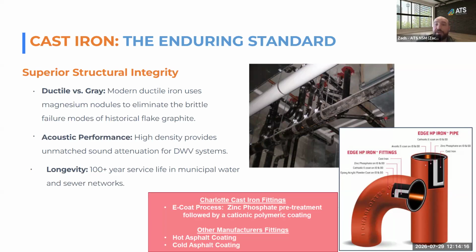But getting into unique applications like underground parking garages and commercial kitchens, where they have a high degree of FOGs, the fats, oils, and greases. That grease can off-gas and release highly corrosive gases into the piping. So even though the water with the fats is not necessarily highly acidic and not caustic, the off-gassing can very much corrode general piping.